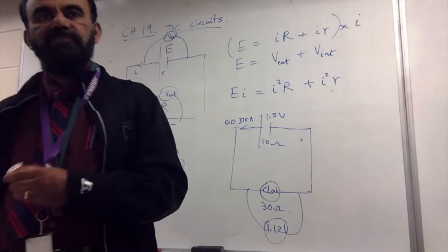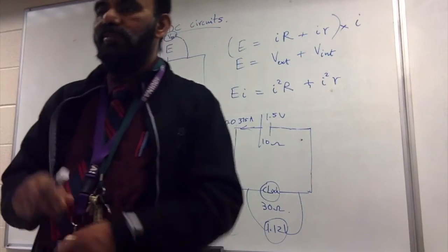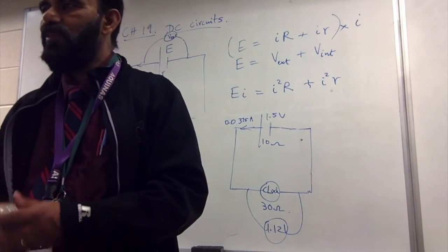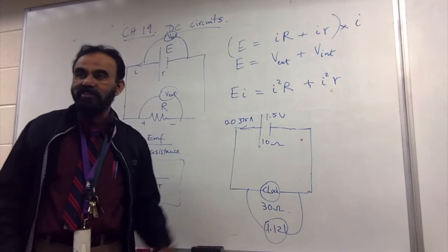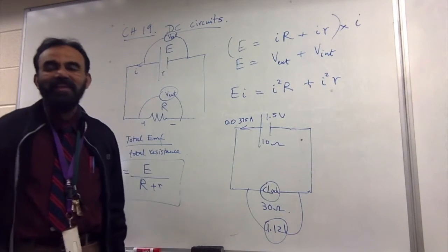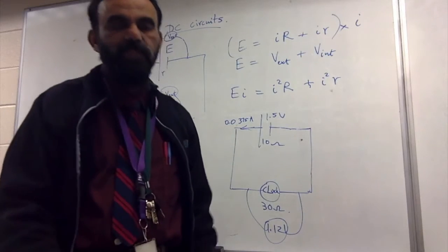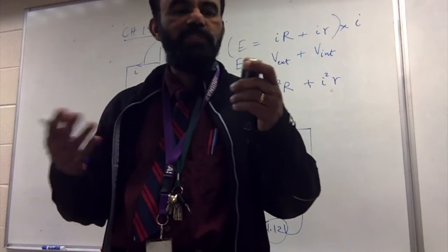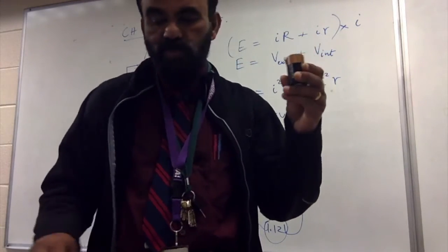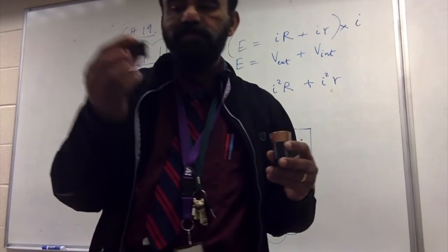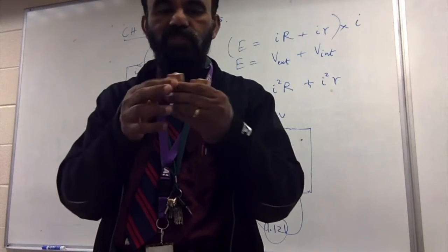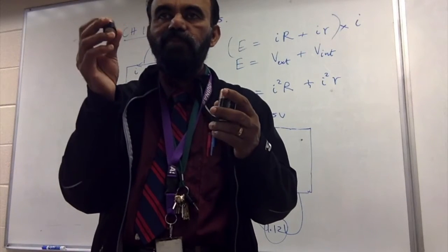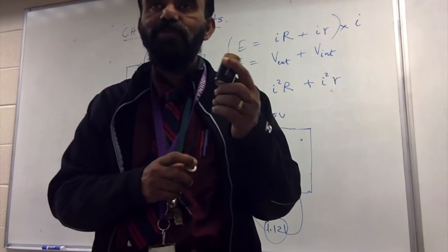But then if it is unfit for the clock, you can still use it for maybe a digital wristwatch. It'll work because it depends on resistance. So the cell doesn't die at all. It just keeps being used. The internal resistance is what changes over here. This one has internal resistance which is on the higher end to start with. So this cannot be used where this one originally is supposed to be used.